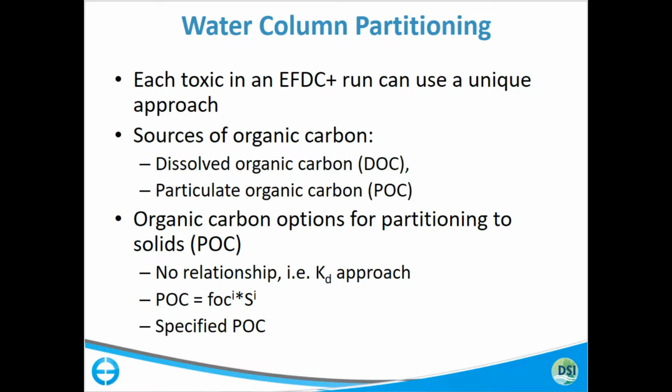Secondly, dissolved organic carbon is not a constituent that is simulated directly in EFDC in the toxics model. It is supplied externally as an input to the processes going on in the model. And there are a couple of ways you can do that.